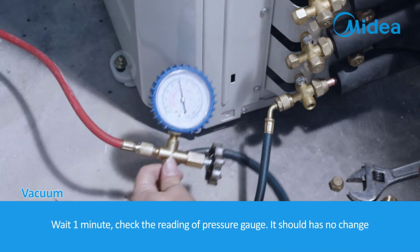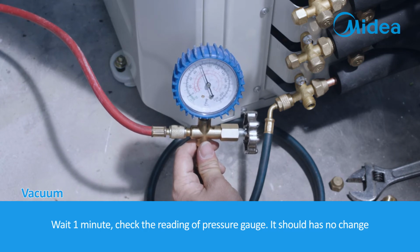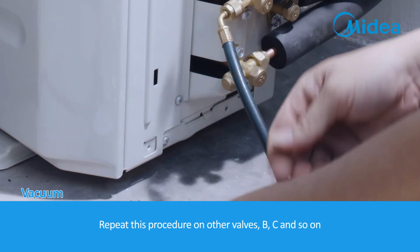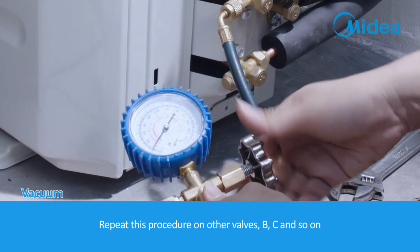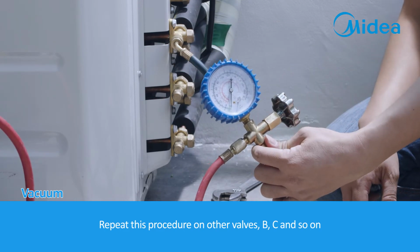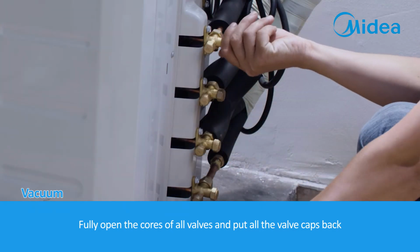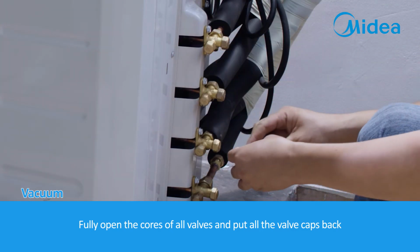Wait 1 minute. Check the reading of pressure gauge. It should have no change. Repeat this procedure on other valves, B, C, and so on. Fully open the cores of all valves and put all the valve caps back.